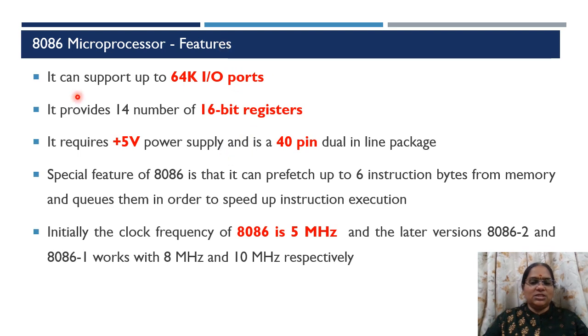Coming to the other features, it can support up to 64,000 input-output ports. You have registers available in the processor, which you use for assembly language programming. You have 14 16-bit registers. Just a 5-volt supply is enough to make this processor work. It is a 40-pin IC.